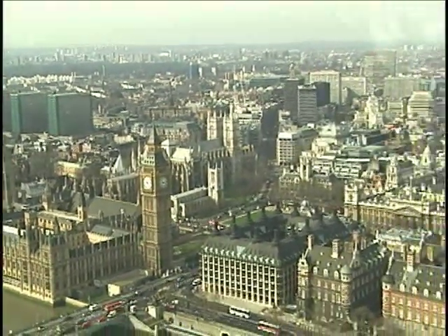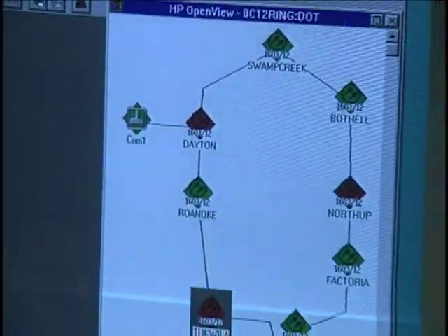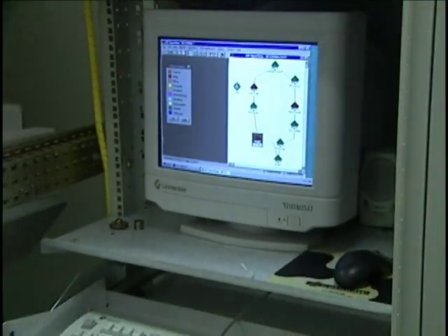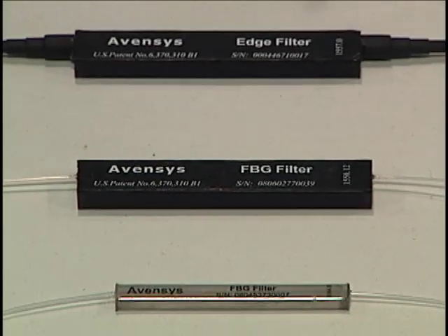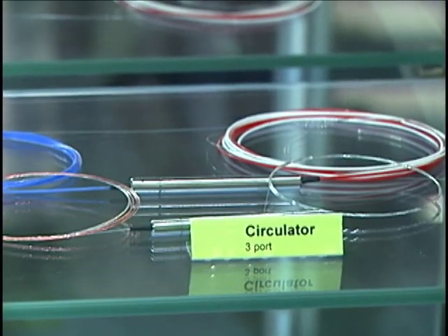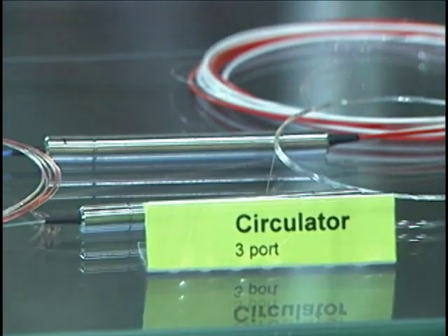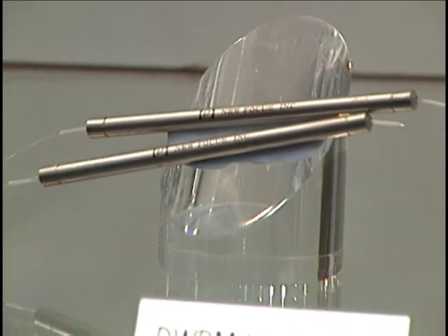These networks use DWDM in ring architectures, which required an optical solution to add and drop wavelengths at multiple access points throughout the physical ring. The fiber Bragg grating provided the ability to filter specific wavelengths, and when integrated with the optical circulator, would provide the add-drop function. Other passive products evolved for use in WDM, including the interleaver.